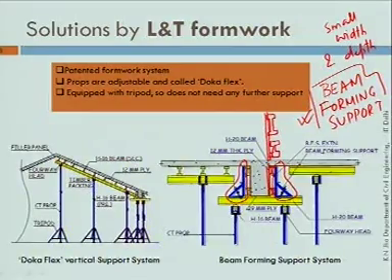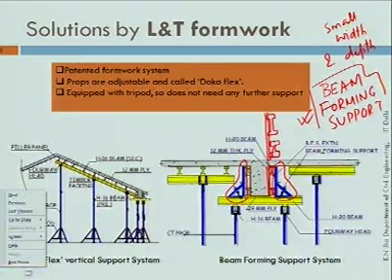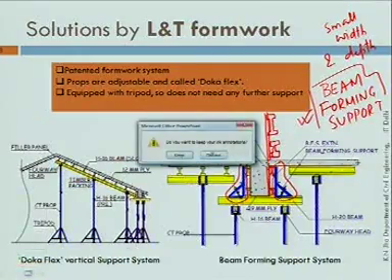So with this you can manage maybe up to 600 to 700 millimeter depth of beam without using any timber. Now I will show you, if the beam thickness and width is more, how the arrangement looks like. I will just try to make one small sketch.